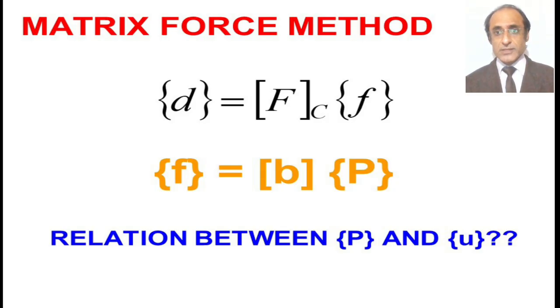That is the main difference between the stiffness approach and the flexibility approach. Another difference is that here the p vector defines the state of the forces. So here we don't talk of the degrees of freedom. The matrix size is dictated by the size of vector P.